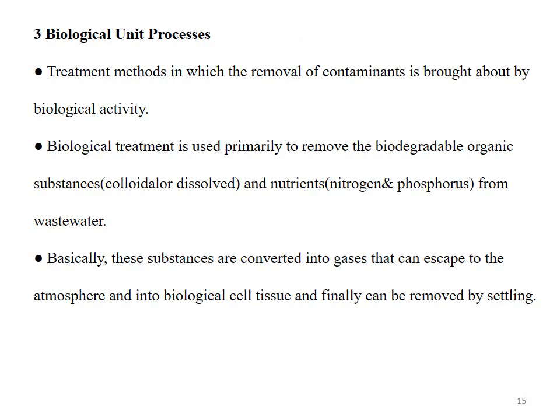Biological unit processes can also be used for wastewater treatment. Treatment methods in which the removal of contaminants is brought about by any type of biological activity are named biological unit processes. Biological treatment is used primarily to remove the biodegradable organic substances.